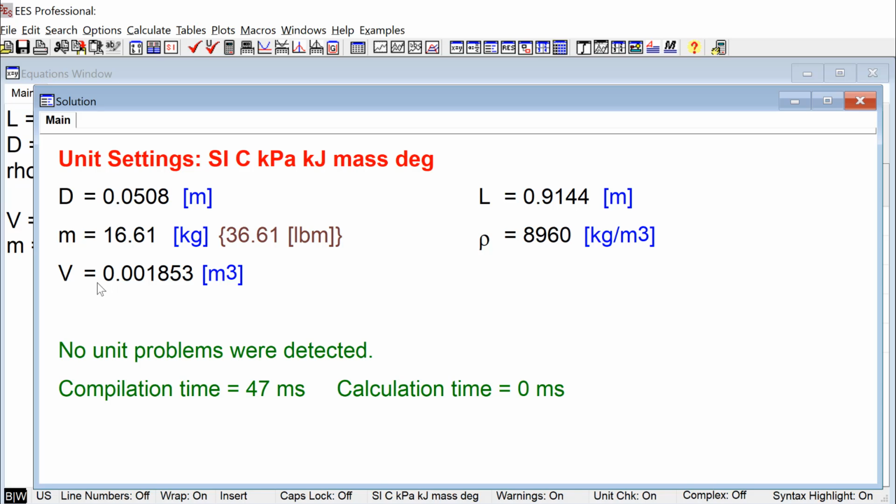It's very important that you understand that the variable's value in these secondary units is only shown for the user's benefit, and the value is never used in an actual calculation. The value that EES uses in the calculations is the one with the primary units. You can also set secondary units using the variable palette or the variable information window as we did before for the primary units.